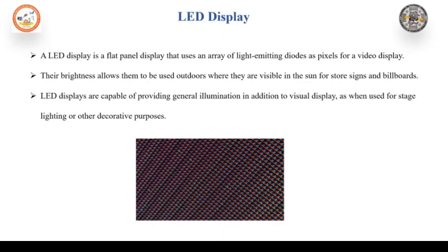Free electrons are in the conduction band energy levels, while holes are in the valence energy band. Therefore, the electrons are at higher energy levels than the holes. For the electrons to recombine with the holes, they must give up some of their energy.